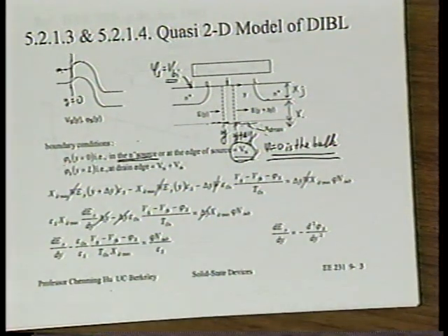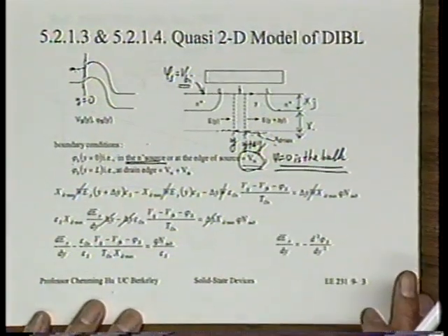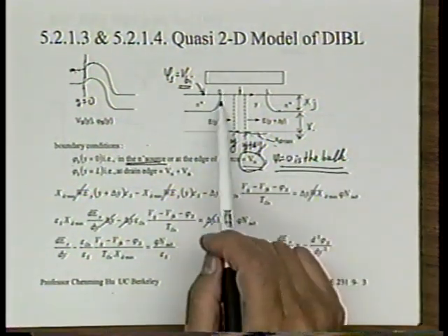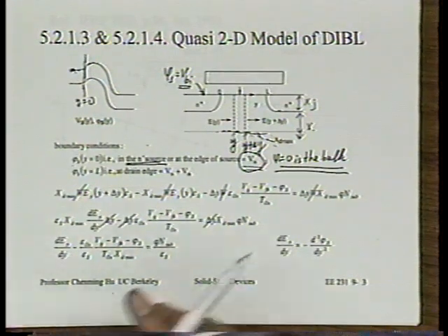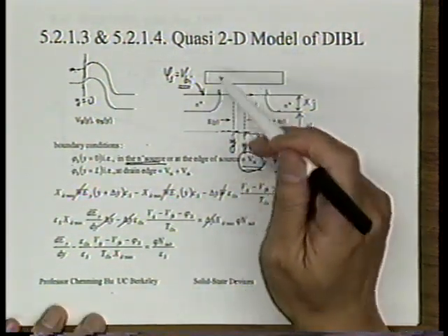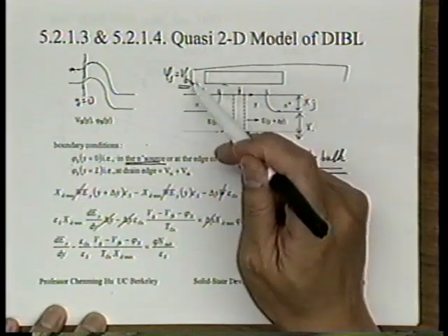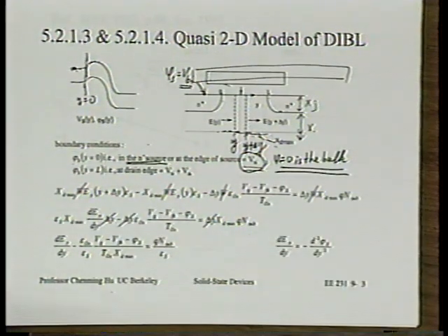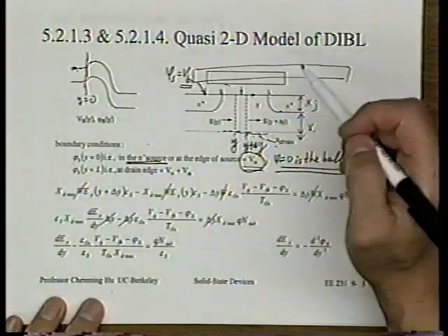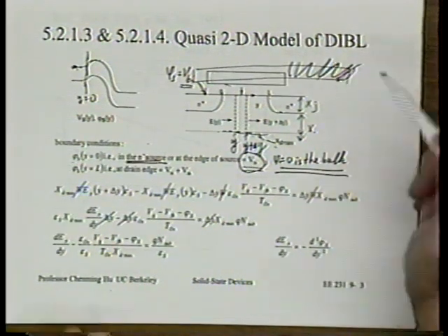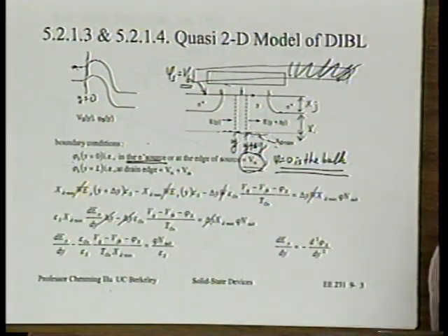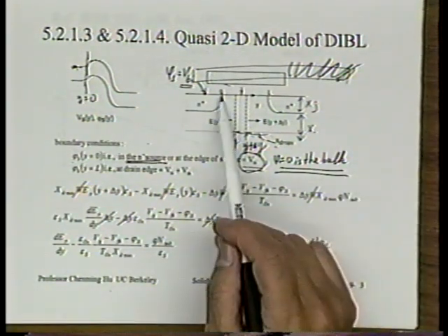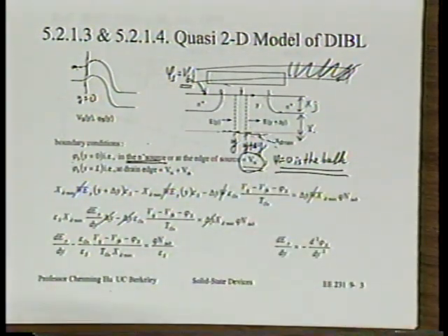So the L you use there is not the length of the gate. That's right. In device physics, we always emphasize the channel. When we say channel length, we always mean this channel length. We don't care whether the gate is here or the gate is here. Okay, in case they are different, we always talk about channel length. The gate length is very important from technology consideration, from lithography, overlap capacitance. But when we talk about short channel effect, we always talk about this as channel length, sometimes called effective channel length. Good question.